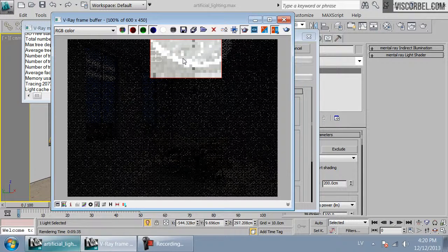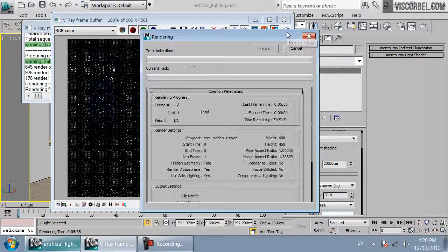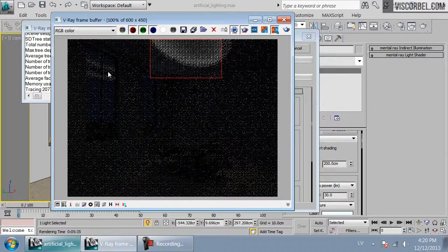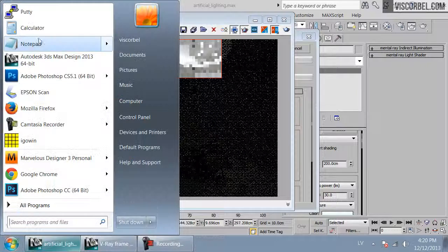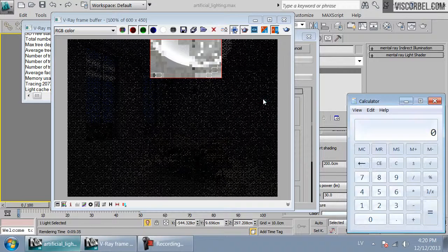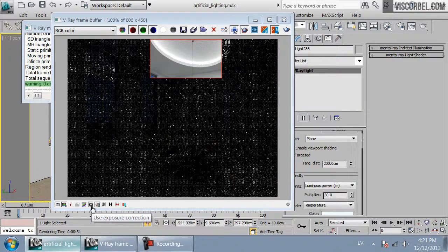And right now it looks much too bright. So let's bring down the luminosity to maybe, I don't know, 30 lumens per light. Since there are so many of them, you can actually calculate the total lumen output. Let's say 120 by 30 lumens, that's 3600 lumens of light for this whole area. I think that's not too bad. We might need to adjust our exposure.